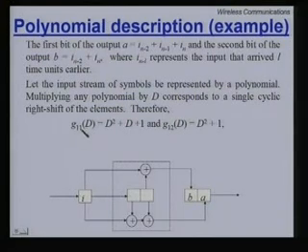Yes, it is the generator polynomial which corresponds to how the first input bit is associated to the first output bit. G12 represents the relationship between the first input bit, and we have only one input bit, to the second output bit. Had there been two input bits and three output bits, you will have G11, G12, G13, G21, G22, G23.